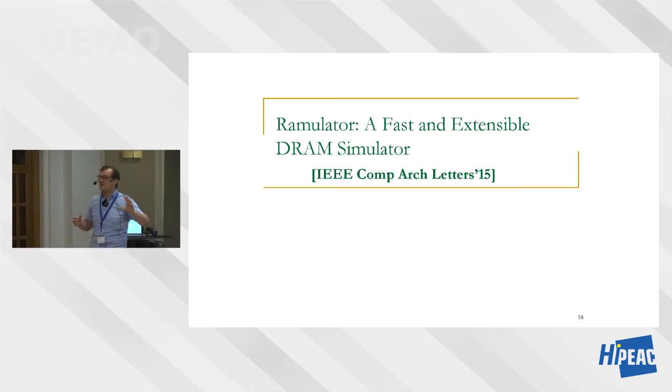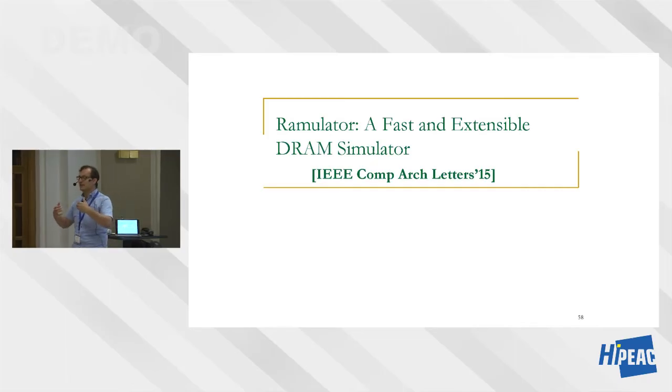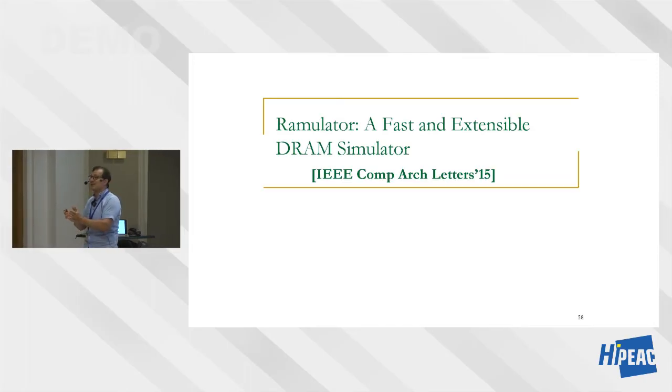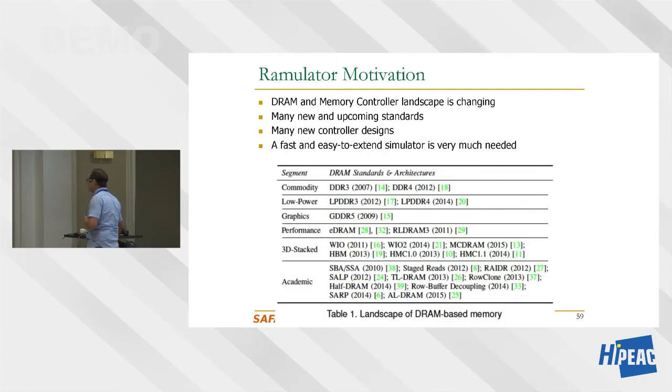We showed on real systems that if you have a dual core processor, one application can deny service to another because the memory controller is unfair. It unfairly treats different applications. So we wanted to provide solutions to that problem. For that, I needed a memory simulator. So this is what we designed in 2006, and over time we improved it, and we open sourced it in 2015. And the open source version is very different from what I started with.